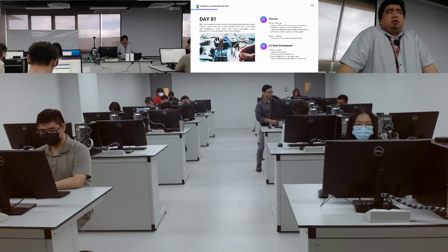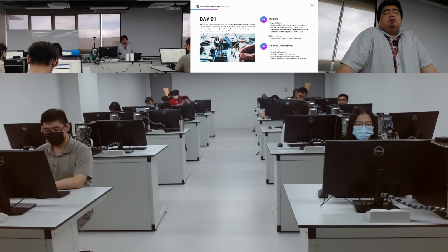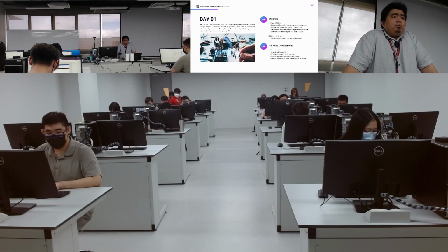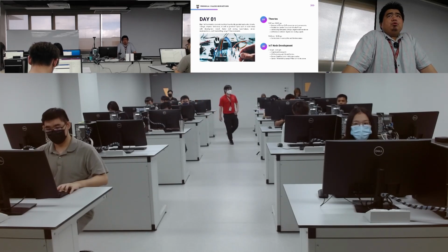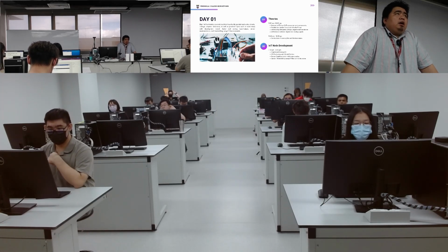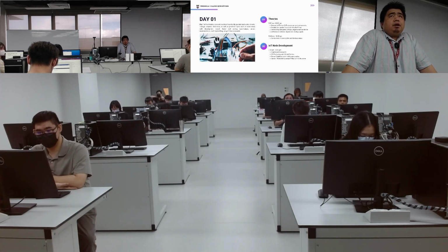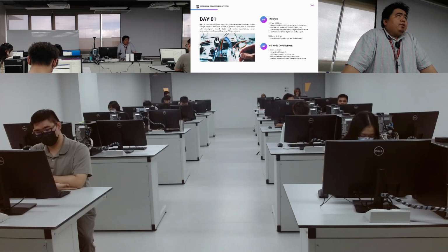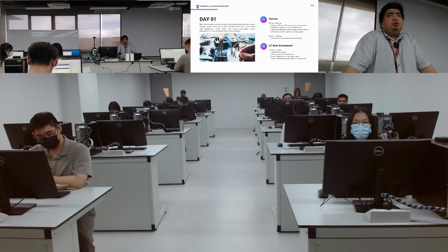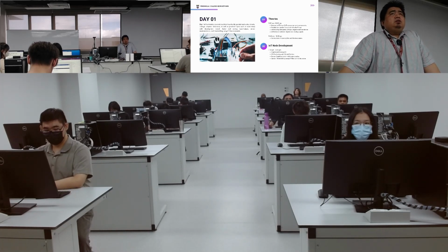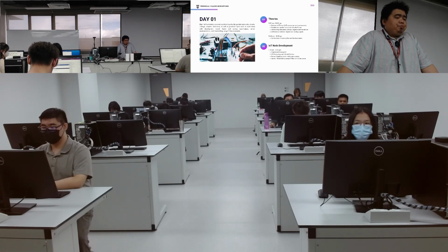But digital and analog signals are important, so that you can differentiate between them, right? For example, for digital input we use our push button, while for analog input signal we use our potentiometer. So the result of analog input can vary from 0 up until 4095. Meanwhile, digital only consists of 0 or 1, right?